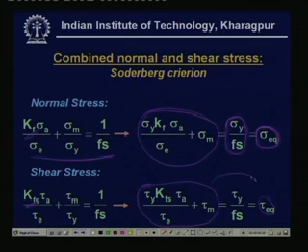So, we write this as the shear stress equivalent, and the shear stress yield point by factor of safety is nothing but the design stress. This idea will be taken up for getting an equivalent normal stress or an equivalent shear stress.